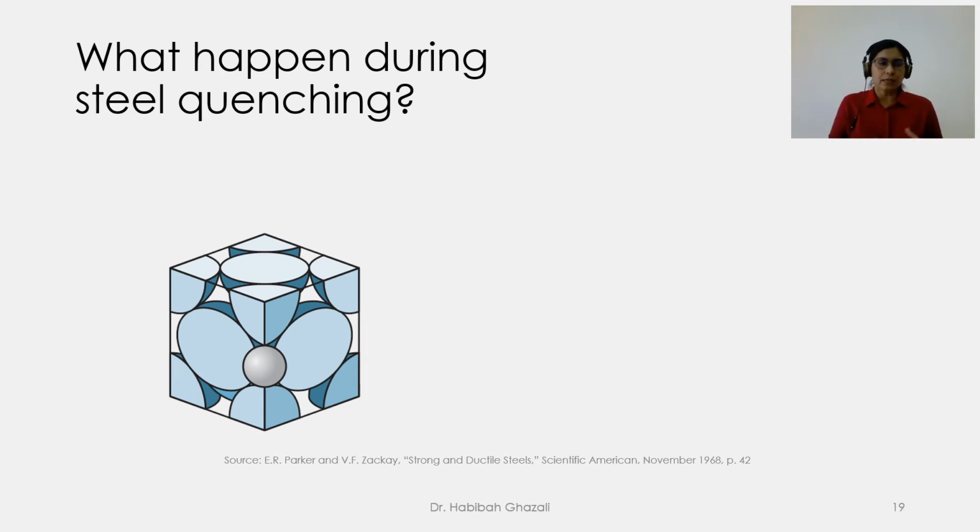At room temperature, if we have an already solidified steel, we will have a steel that consists of ferrite and cementite phases. Then we perform heat treatment in which we heat these materials to decompose these two phases to become austenite again. So we heat it up, everything will transform into austenite again. We know that austenite has a crystal structure with carbon atoms residing inside the FCC unit cell, as you can see here.